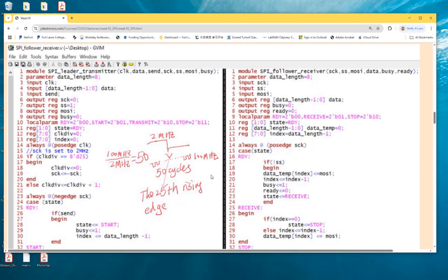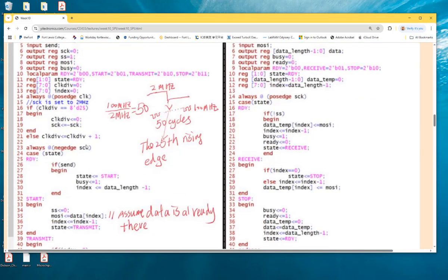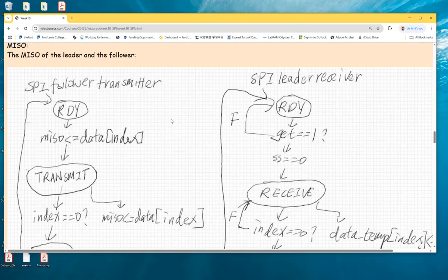This happens when you are using a microcontroller. You're looking at the registers. You probably need to write a register value over there to define the SPI's mode. So in that case, the mode can be changed for that digital device. But I don't think we can change it here, because all of these are already defined. It's the negative edge to put the data on the line, and the positive edge to take it in, right? Okay.